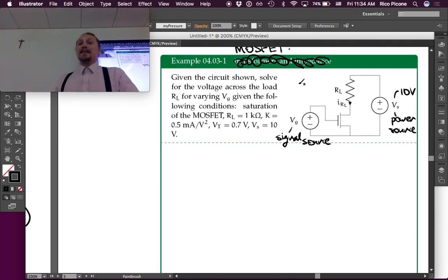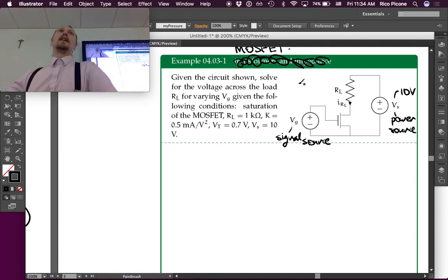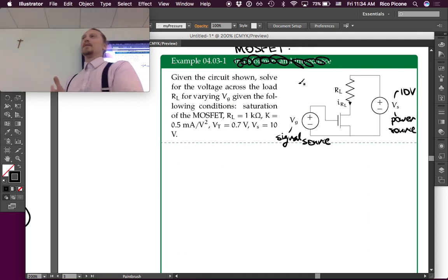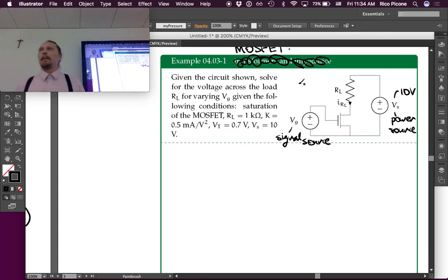So that's the problem. And we could apply this circuit immediately. We could walk into the lab and apply this circuit. A motor doesn't act as just a resistive load, as we'll discover. It's an inductive load, which is a little bit more complicated, but all you really need to do is add a diode in there and you're fine. So we can use this for a motor load, but this isn't a motor load because it's not inductive. It's just resistive.